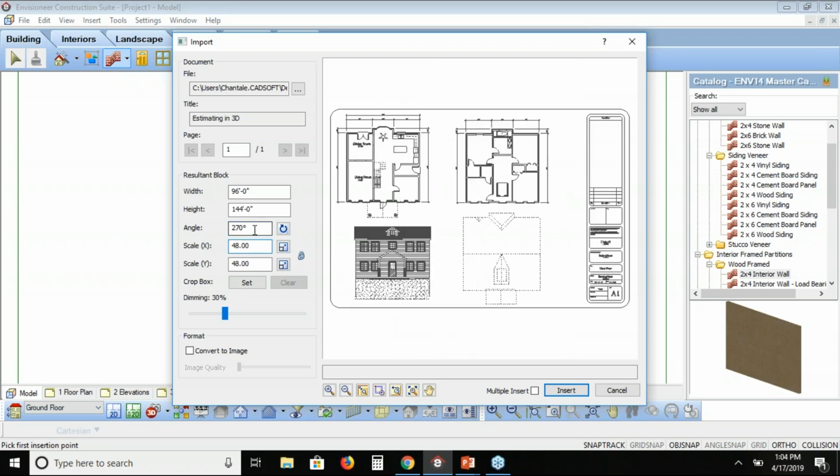Again, thinking about those really bad PDFs that you get in, that they might be off on a skew. Someone actually put it on a flatbed scanner and they made a PDF out of it. This little button right here, Pick Angle, will allow you to straighten that out. It'll allow you to pick 2 points and make that a 90-degree angle. So even if it's off on a horrible little skew, you can bring that right back down.